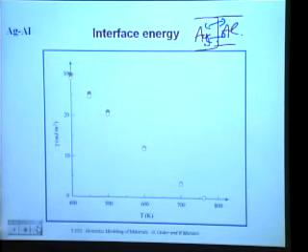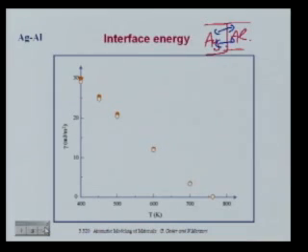Okay? So let's say that this was experimental data that you'd gotten. If you had no idea about the physics of that interface, you would probably not apply the right simulation. Because if you took a hard silver-aluminum interface, pure silver, pure aluminum, and did all the beautiful stuff, temperature dependent, had the vibrations, maybe even the electronic excitations, you will not even get nearly close to this answer. Because the decrease in interface energy with temperature is purely driven by interdiffusion in this case.